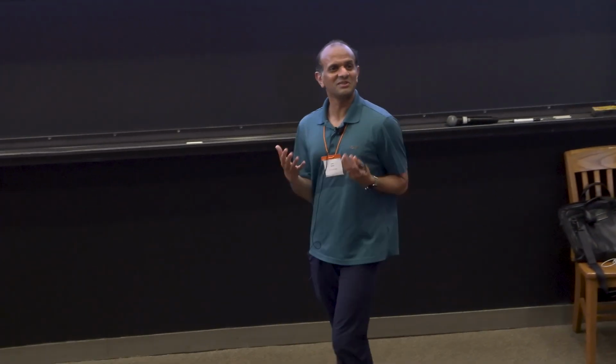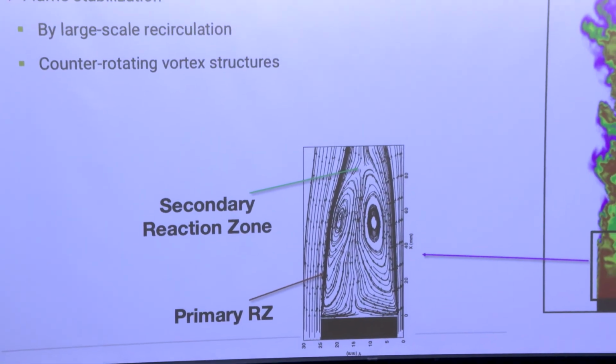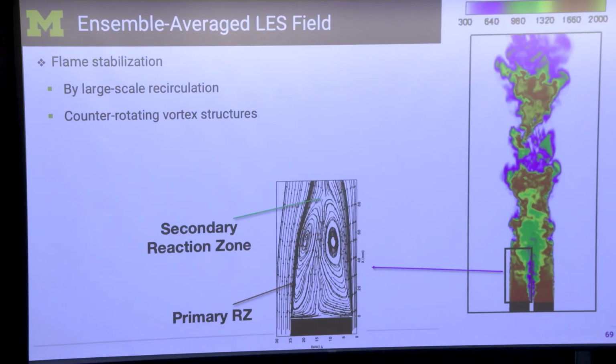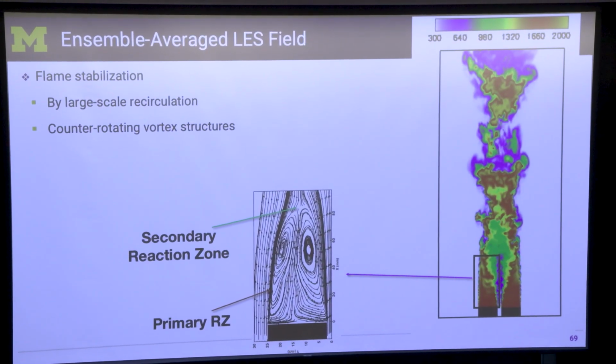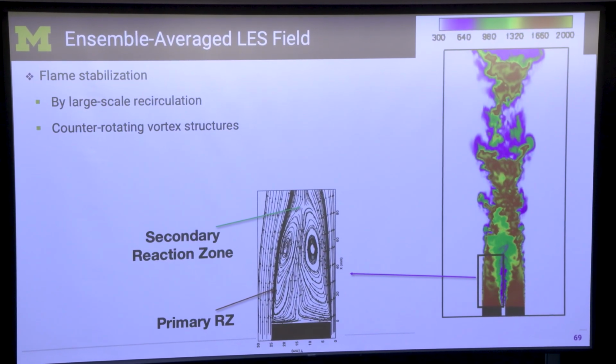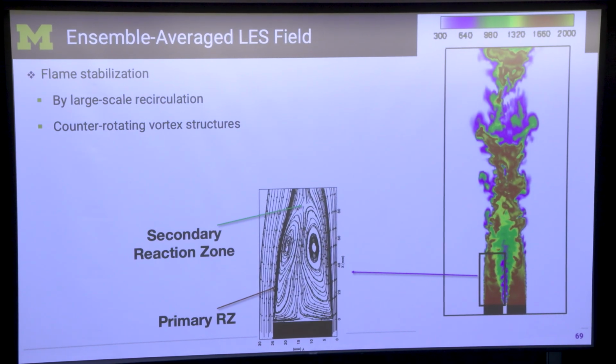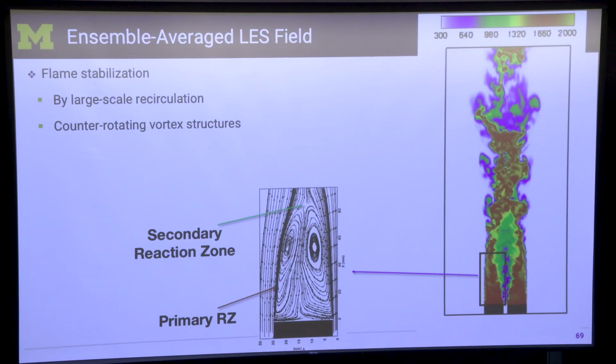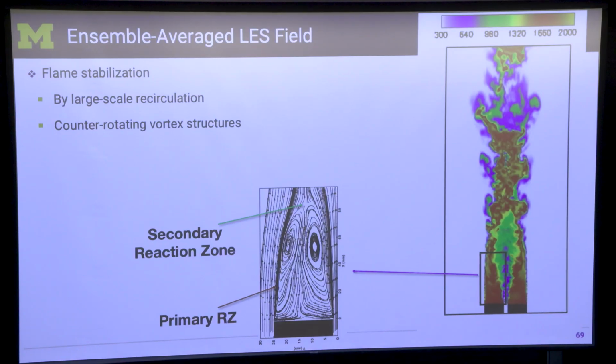And so we could do these complex flows, right? The thing that we realized from this is that what LES is good at capturing are these kinds of problems where you set a boundary condition. It doesn't matter what models you use. We'll talk about the models tomorrow. You use some set of models. The combustor needs to have some physics that's changing with time without you adjusting the boundary conditions, okay? Which it turns out aircraft combustors and stationary gas turbines do quite often.